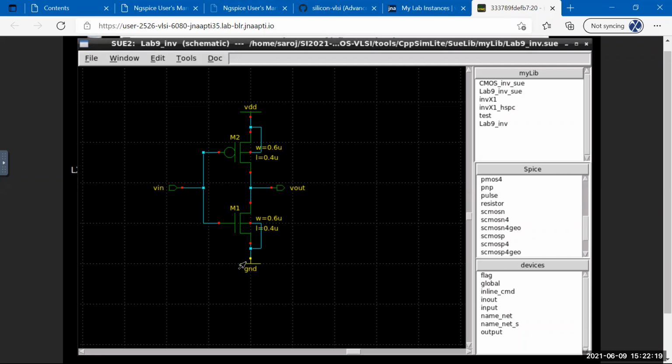It's just the way we are going to write our test bench. I'm just going to show you one way to write the test bench where you can use global input, output, and all that. So it's mostly for demo purposes. Like I just said, in digital standard cells, the VDD and grounds are almost always global, but when you're doing custom digital or analog design, we never ever use globals because that's a nightmare for making mistakes.